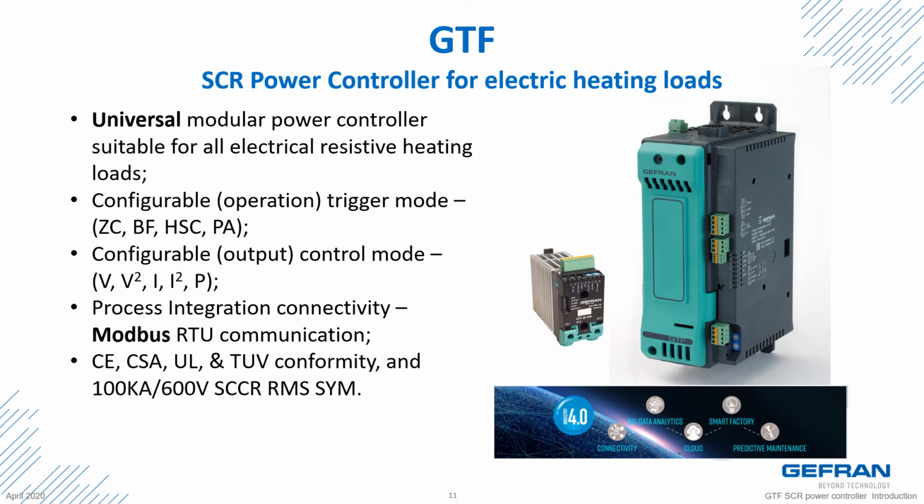It provides process integration connectivity through Modbus RTU communications, and has conformity to CE, CSA, UL, and TUV, and also a 100,000 amp 600 volt SCCR RMS symmetrical rating.